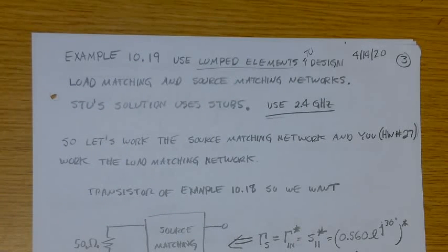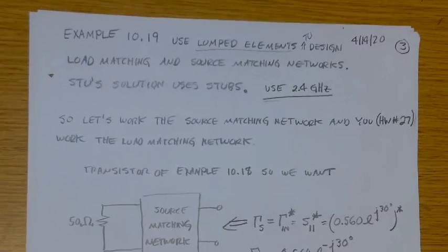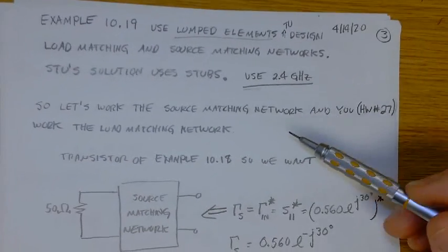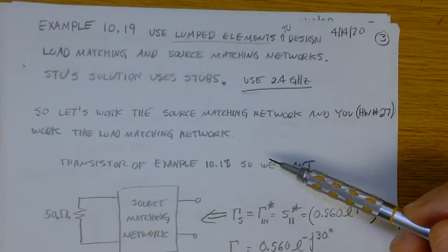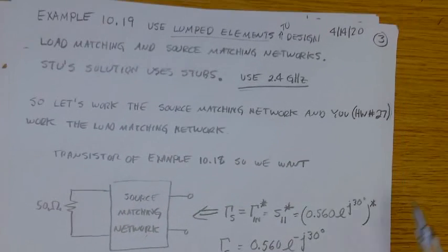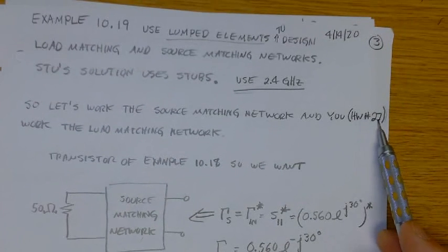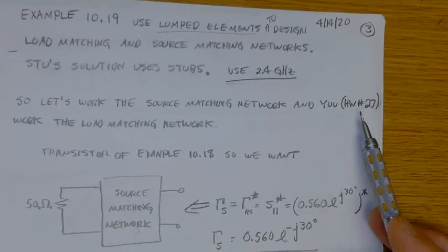So you look at both methods. It's good to remember how to do it both ways, both lumped matching using circuit elements and stubs. I'm going to do the source matching side, and then for homework, you do the load matching side. We'll review that homework when we get through this.